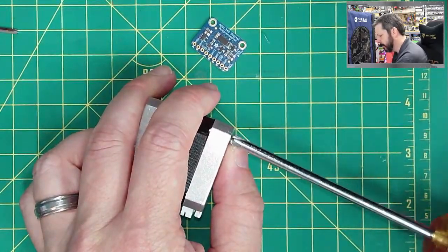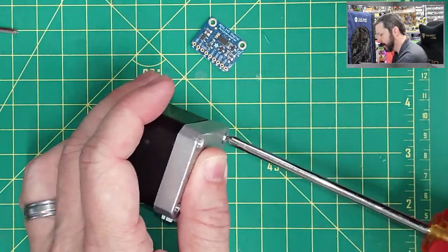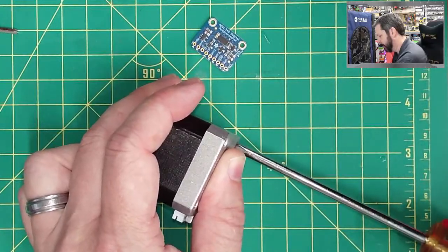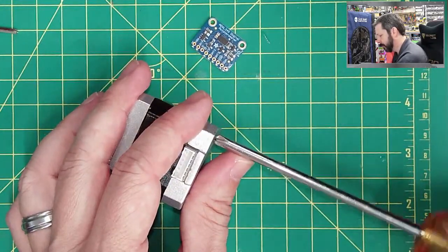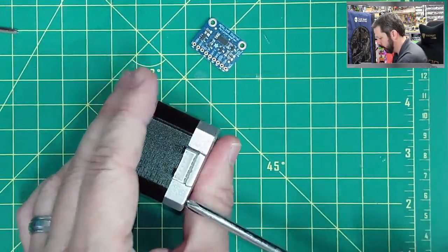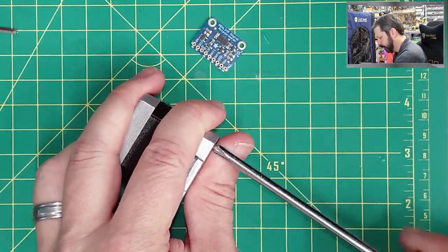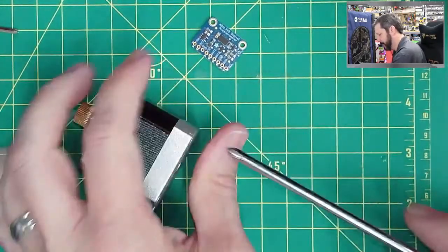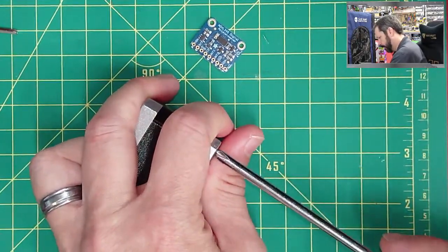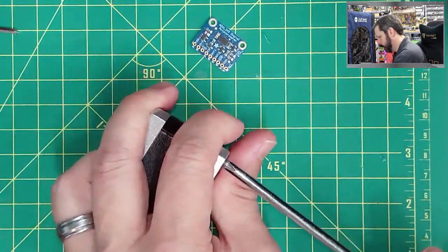You're not going to get one from the factory that way, but only some of the times when you change out a board or something like that and the steppers just aren't doing what you anticipate, you might have to rewire the cable. But that doesn't seem to happen very often anymore. As things get more and more standardized, with more printers out there basically all doing the same thing, you get less of that happening. And now our stepper should do what it's always done.